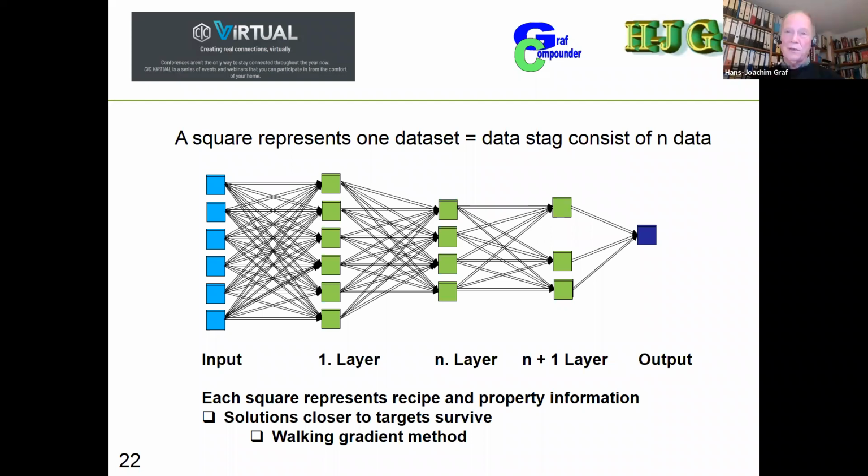And I thought about that because we used not even the same mixing machine for that experiment. So you can make up your mind that way in your analysis, as you say, molecular weight shows up in a certain way. If it comes to synthetic rubber, it's a little bit easier because a lot of the parameters we target today in polymer development is towards processing and process design. And we still have the molecular weight as a main influence on physicals, and we have the long chain branching, for example, and the molecular weight distribution. We have a little bit less influence, but more on the processing then.